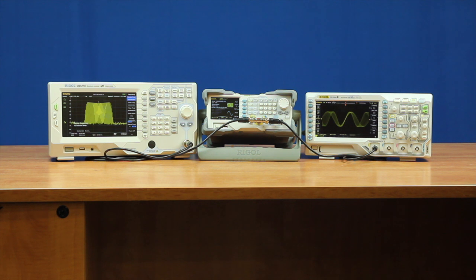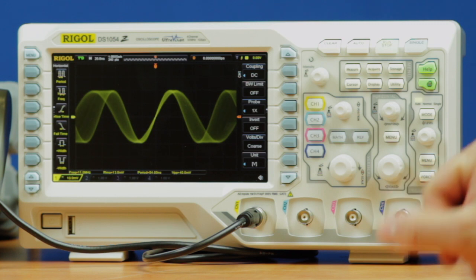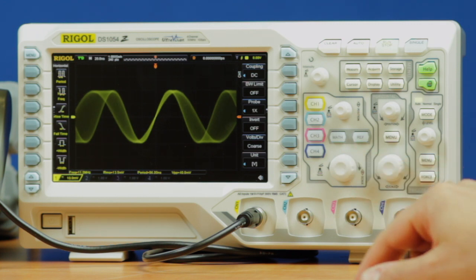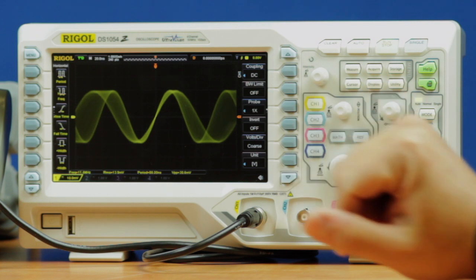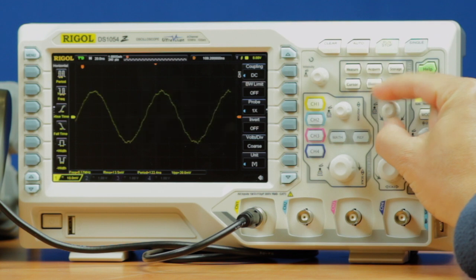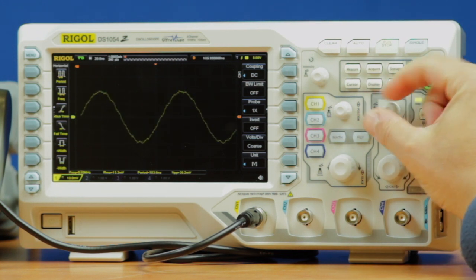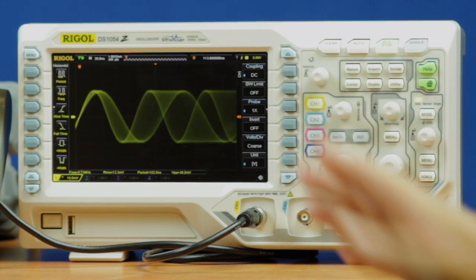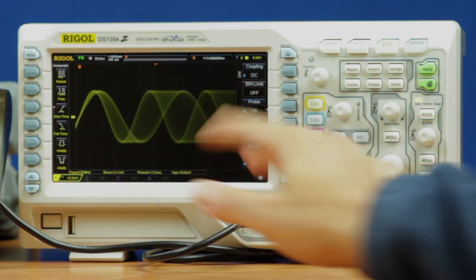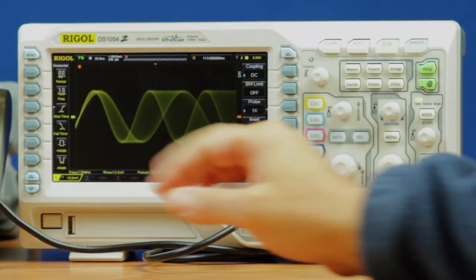Now I've set up the three instruments using the FM modulation setup files. Then I activated the output on the generator, and this is what we see. On the scope, this is an interesting example of how you see the frequency changing. That is, the time between peaks is changing. Because we're triggering in the center, that point is solid. If we move that trigger point to the left of the screen, now we can see as you move over in waves, you get more and more discrepancy as the frequency is changing from shorter frequencies to longer frequencies.